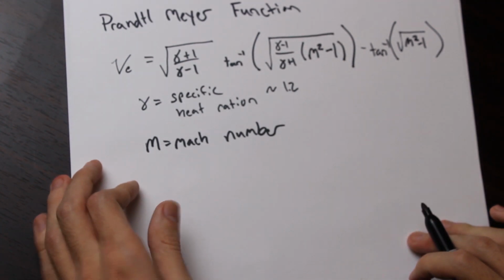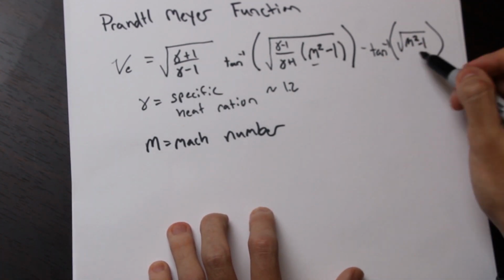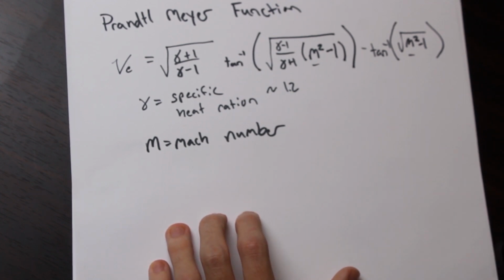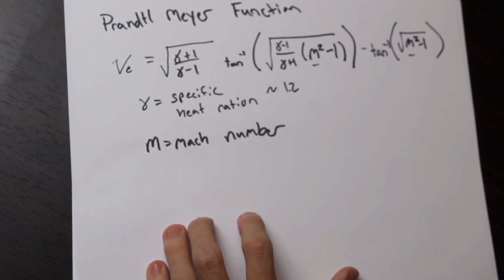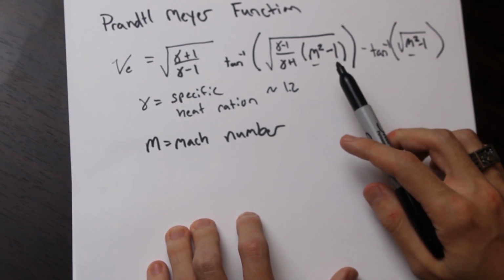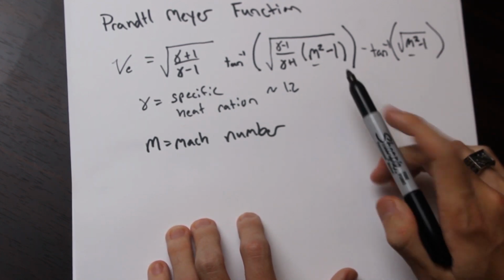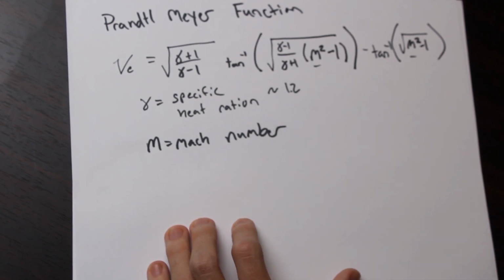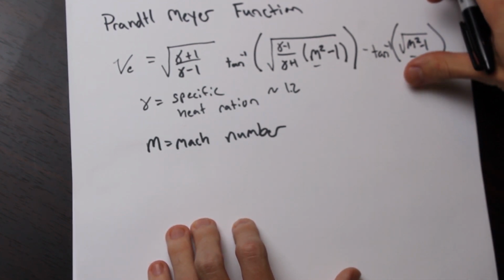And just some kind of important trends here. The way Mach behaves in this equation, the faster the flow is, the less you can turn it before you have problems. So what you're really saying here is that slow-moving flow, you can turn it around a tight corner. Fast-moving flow, if you try and take it around a tight corner, you're going to have problems.